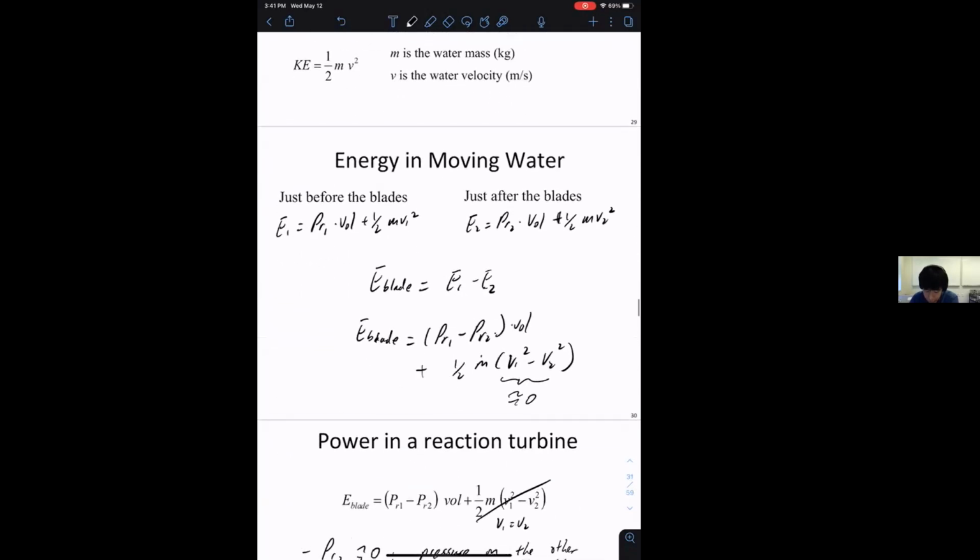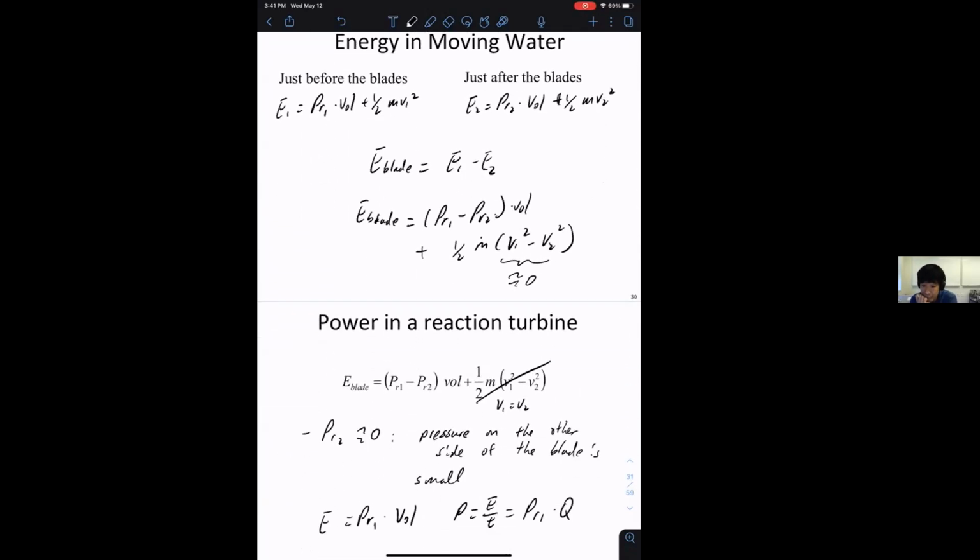Student: If pressure makes that much of a difference in these things, would that mean that they're less efficient? Because obviously more pressure means more friction when turning the turbine. Right, that's why you don't have 100% efficiency. But are reaction turbines less efficient than impulse, or roughly the same? Roughly the same. If you pick the correct kind of turbines, you both get about 60% efficiency. They're not inherently less efficient.